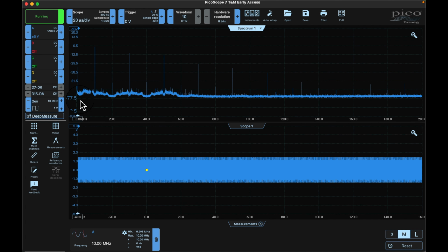I just want to point out that we have frequency across here and decibels right here. So these are dBs, and I can change the kind of dBs, like dB millivolts or whatever, along here. But this is measuring decibels because decibels help you look at very small things and very big things in the same picture, right? And across here's frequency, where down here I got time and volts up here. So that's the main difference, I'm just looking at a whole bunch of different frequencies.